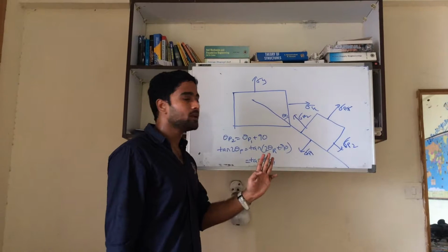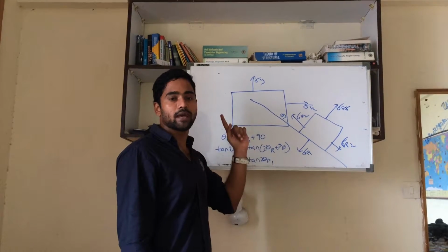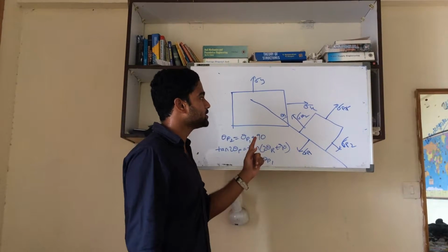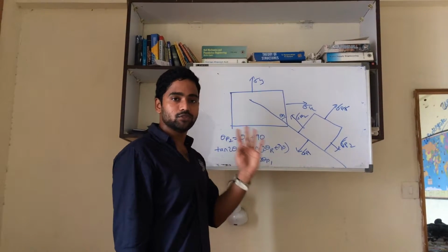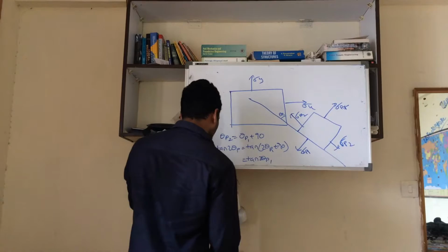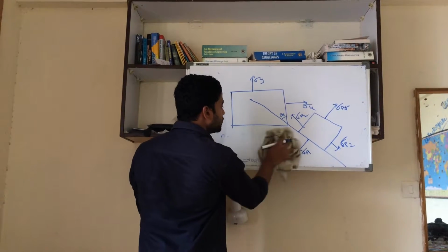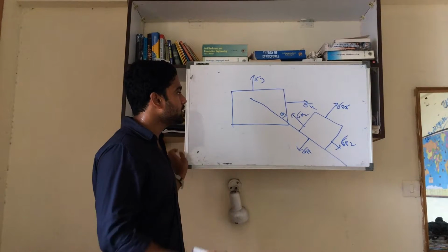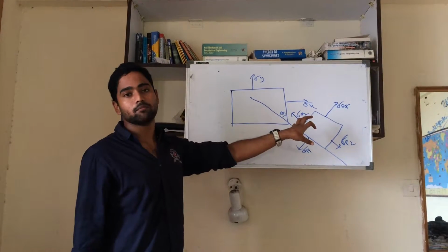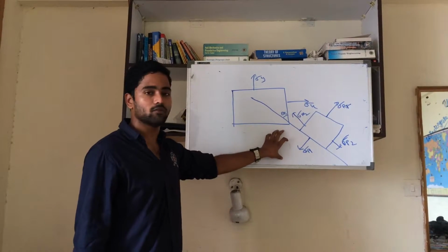For a triaxial state, you will get three such stresses, and the maximum of all these three stresses will be considered as the absolute maximum, and the minimum will be considered as the absolute minimum. So this is how the location diagram will be shown. That is, if in an examination they ask you to show sigma p1 and sigma p2, this is how you have to show.